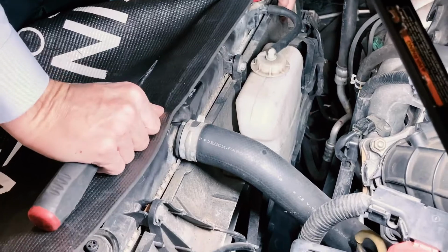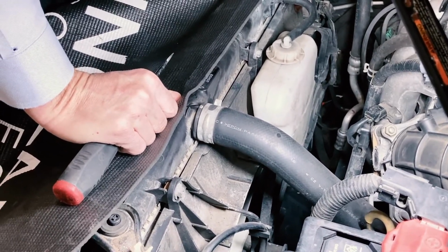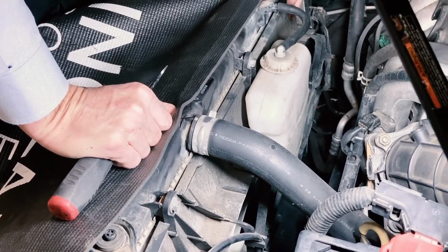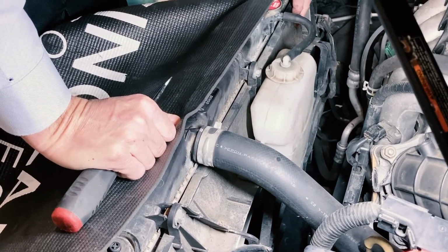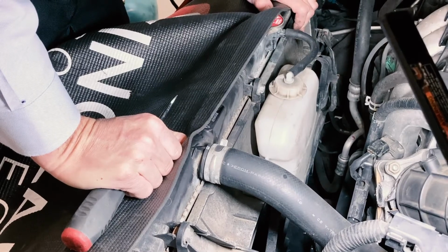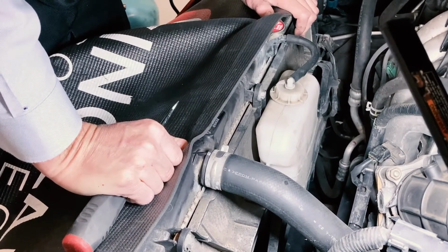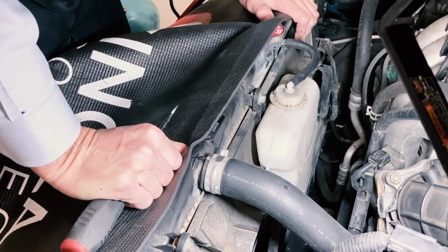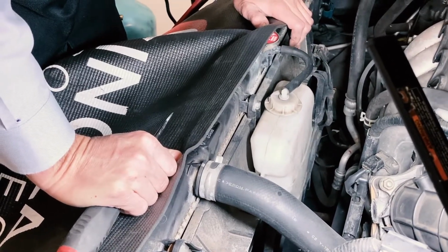By disconnecting the fans, that keeps the airflow from transferring across the condenser. What should happen, if our compressor is doing its job, is our high side pressures go from maybe 125 to 175. And the reason is it's working harder to overcome the ambient temperature.